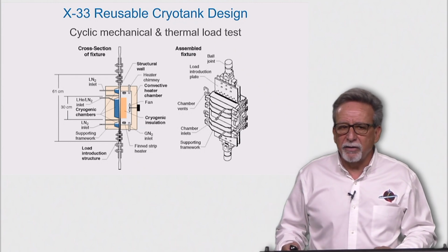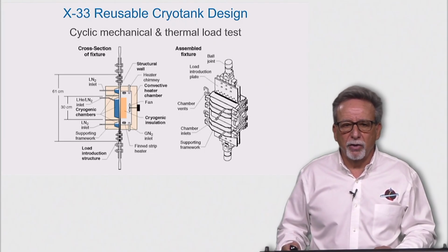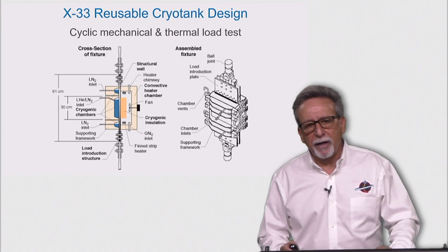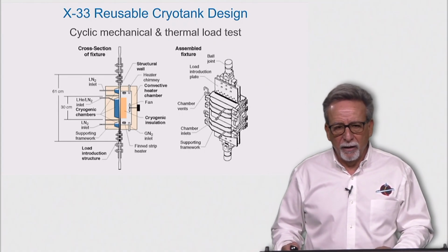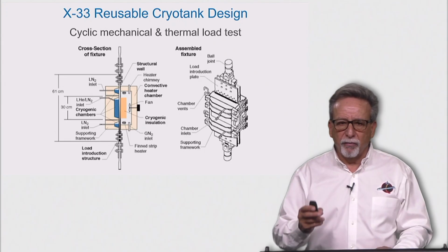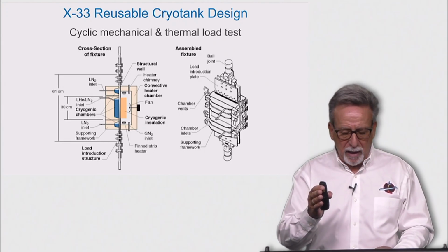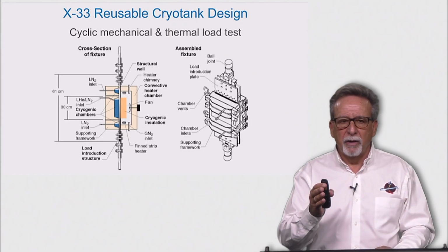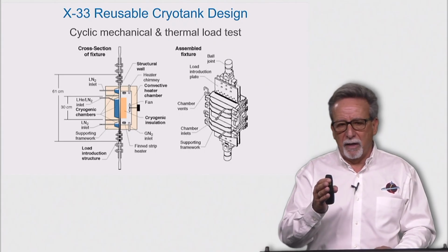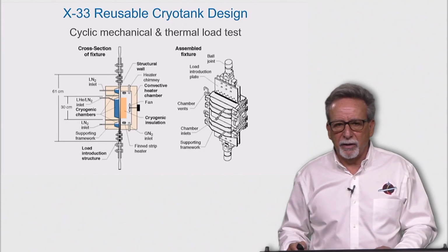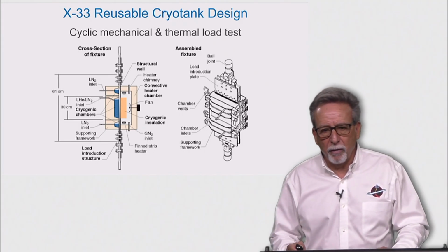During the early phases of the reusable launch vehicle selection process, one of the contractors, Rockwell International, proposed an idea that was a derivative of the shuttle orbiter design for the hydrogen tank and insulation. The idea was to bond closed-cell cryogenic foam insulation to the external surface of the aluminum tank, much like you have on Space Shuttle, and then to bond directly onto that cryogenic foam the silica thermal protection tiles currently used on the orbiter.